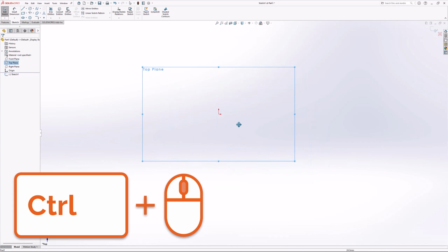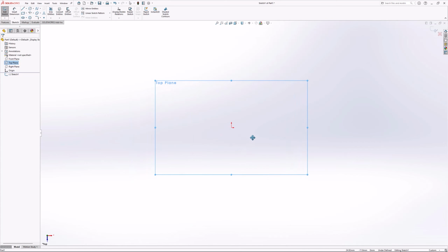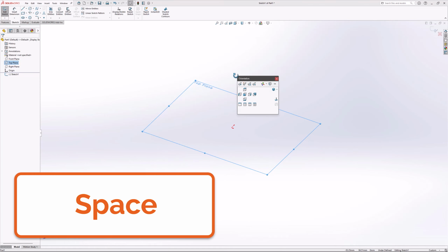Although we are working in a 2D sketch, you will find that this sketch can be rotated within the 3D space too. This can be really useful and aid the selection of certain reference points and edges, but when first getting used to sketching, it can make things confusing. I would recommend that to begin with, try and stay normal to the sketch. So if you do accidentally rotate into a 3D view, which is done by clicking and holding the scroll wheel, tap the spacebar and choose Normal To reset the view.